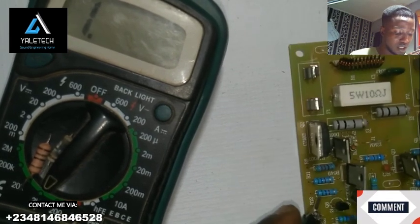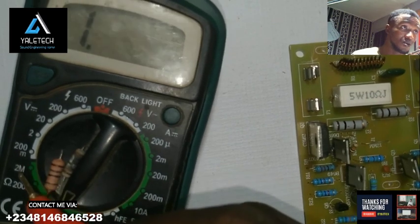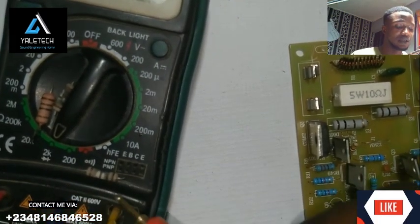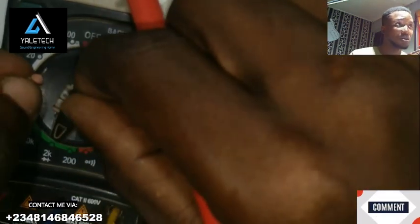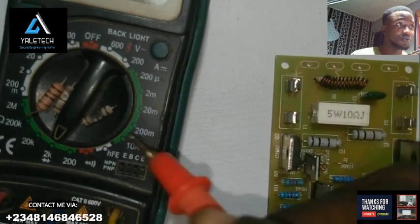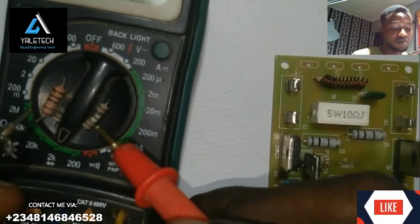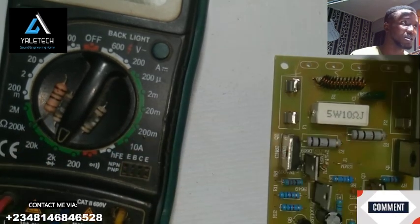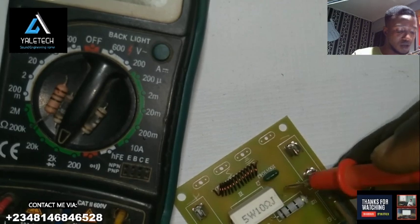So once you test any of them, you check it. None of these is reading at all in your various resistance ranges. That is a good indication that there is a problem with that resistor. So change it. There are some of these burnt ones that are still not 100% burnt, but I can see the damage on them already. So it's good to just change it out to save myself the stress of troubleshooting and causing more issues.